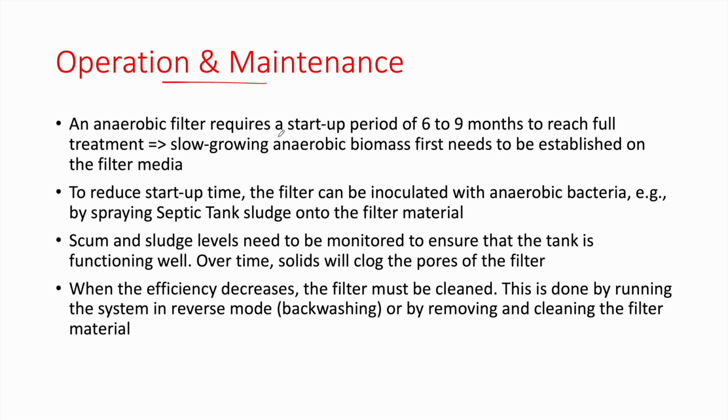The anaerobic filter requires a long startup period, between 6 to 9 months to reach full treatment. So we have slow growing anaerobic biomass that is being established on the filter media. If you want to reduce this startup time, you can take some anaerobic media from another treatment system. For example, you can take some sludge from a septic tank and place it onto this filtering media, just to make this biomass formation a bit faster.